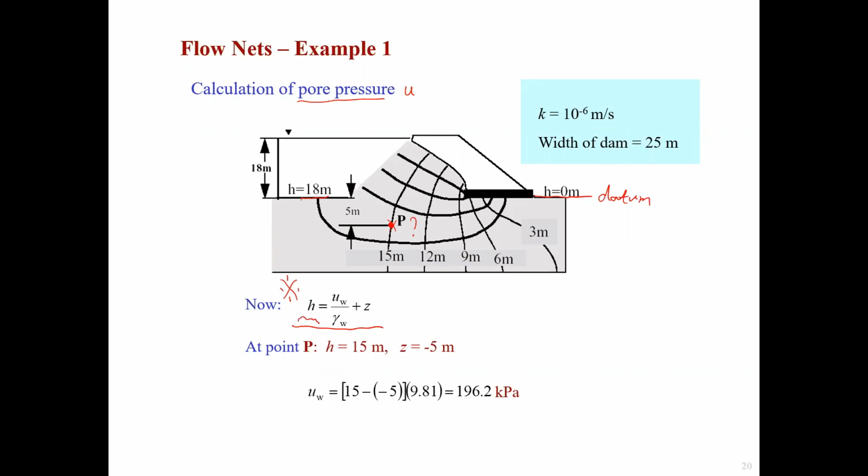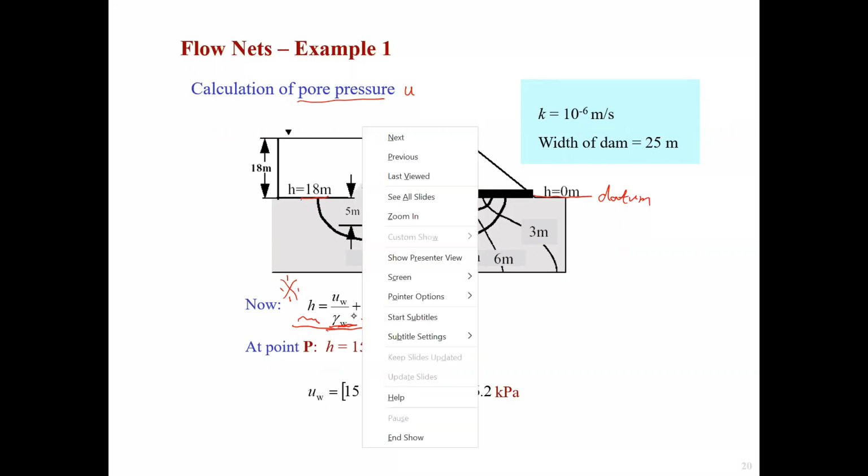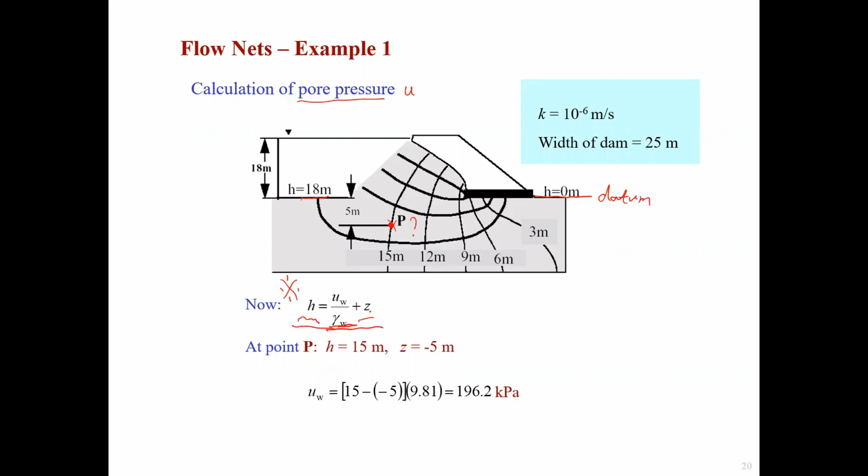So this is the total water height, and that's also equivalent to any value on the equipotential lines. This is the pressure height, and this z is the elevation height. The elevation height only has a correlation with the datum, so it's the vertical distance from the datum.